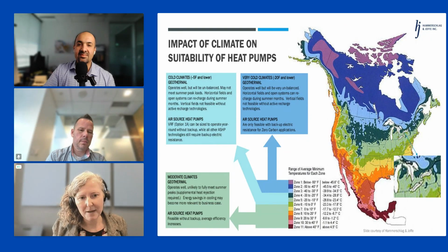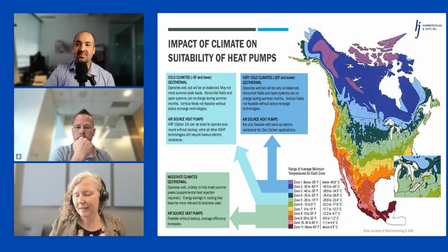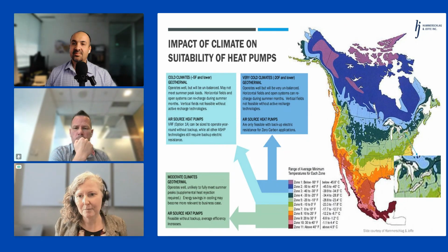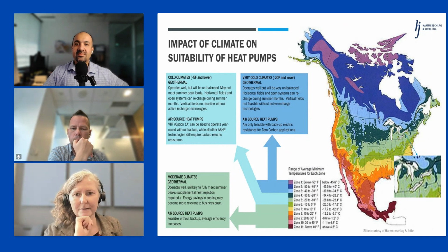But as you start climbing past Ottawa and into northern Quebec, into most of Calgary, you may find that those VRF systems require either a gas backup or an electric backup, or that you may want to consider geothermal because it doesn't require that backup. So make sure that you understand which climate zone you're in when you're picking these systems.